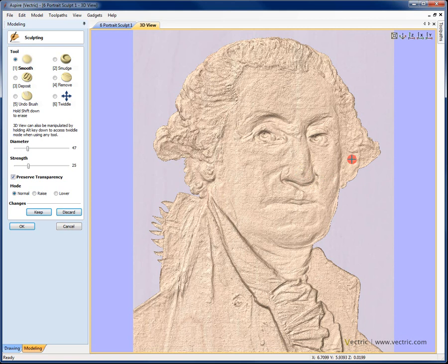If we look back at the original image, we'll see that that's just a highlight that the painter painted in. But because of the way we create this texture component from the image, those highlights will be picked up and given a shape. So they're the sort of things that I need to blend out here. I would do that, just go straight to the smudge tool, kind of 1/3 of the total strength here and an appropriate sized diameter, and just start to smudge that out.